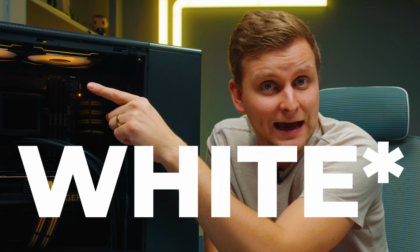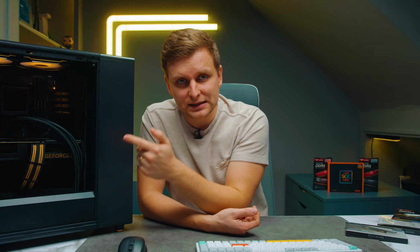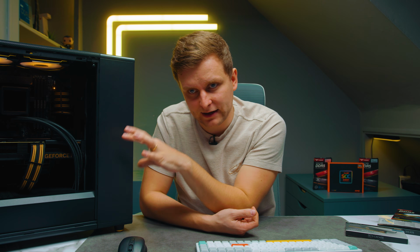On an ASUS motherboard, the yellow light on the motherboard shows that it's in the RAM training cycle. So it's checked the CPU, that's fine, which is the red one. Now it's on the yellow one, which means that it's going to try to check if the memory is working at that speed. When it passes the memory training phase, it's going to move to light yellow, which is the VGA, or the video card check, whether integrated or dedicated. Once it checks that and passes that, it goes to green, which is boot, and then we know we've actually passed. This is going to take a long time on DDR5.